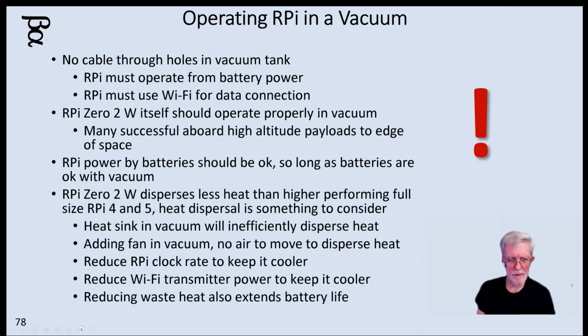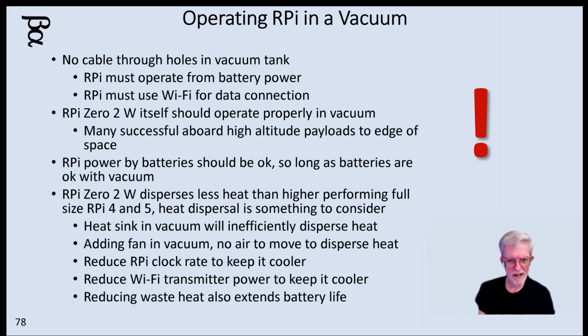So the first thing I had to say was, well, I use a computer. I use a Raspberry Pi Zero 2 W to do my measurements and record data and such. I've got to find a way to get that to operate inside of a vacuum tank at nearly 100% vacuum, nearly 30 pounds per square inch of vacuum inside the tank, on a battery. There's no wires going through for power and data. So it's got to operate off of Wi-Fi inside of an extruded aluminum metal container that has a clear glass top that's 1 inch thick. It's a fused silica glass.